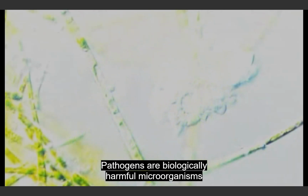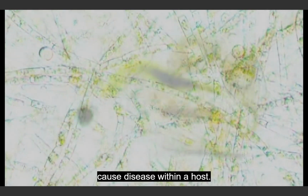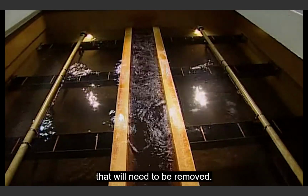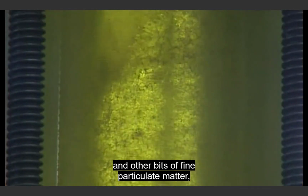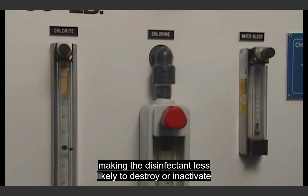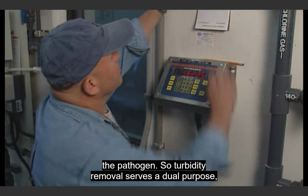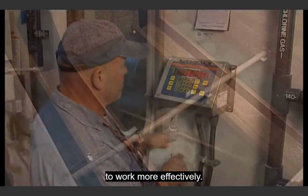Pathogens are biologically harmful microorganisms or infectious agents that might be in the water that can cause disease within a host. For safety's sake, utilities work on the idea that all surface waters may contain pathogens that will need to be removed. Naturally occurring particles, sand, clay, and other bits of fine particulate matter can shield the pathogens from the disinfectant, making the disinfectant less likely to destroy or inactivate the pathogen. So, turbidity removal serves a dual purpose, removing possible pathogens and allowing the disinfectant to work more effectively.